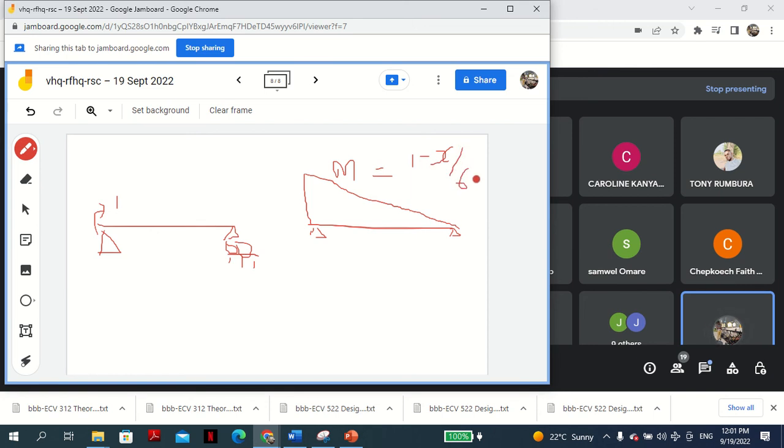And now to get the alpha AA, if you remember, because this is to get a deflection at that point due to a unit moment, we are doing this at A, the definition would be alpha AA, and this would be m over EI.